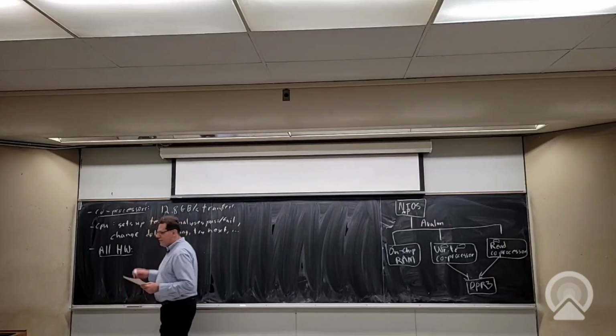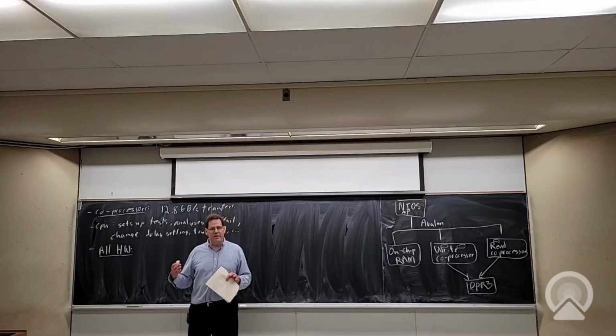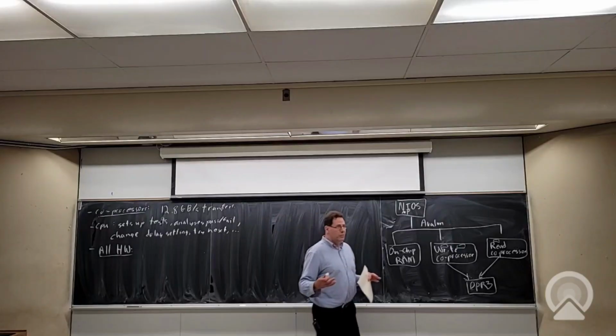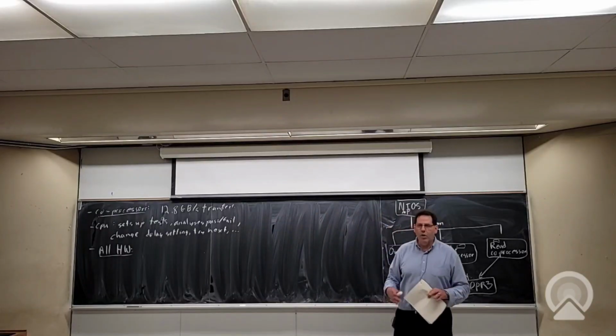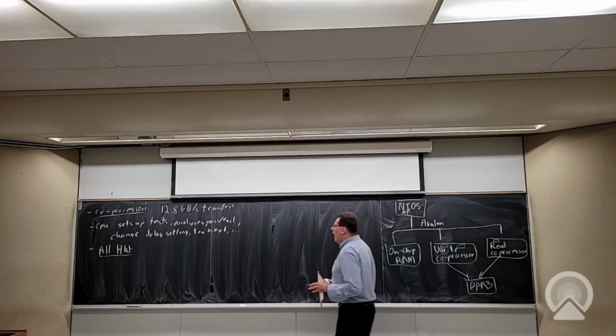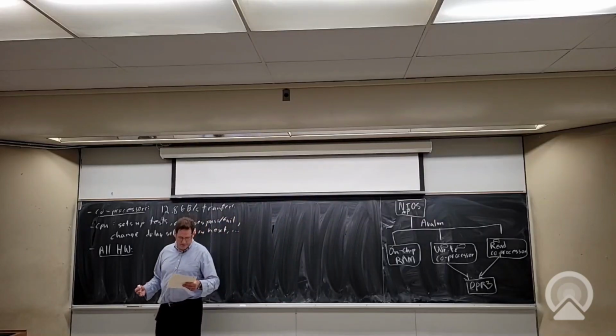And the calibration algorithm also was not fast enough. So they couldn't get to the highest speed DDR standards, and new standards kept coming out. So there was a problem with trying to keep up. It was difficult to modify an all-hardware design with a state machine controlling a data path. And the calibration algorithm still wasn't good enough. Couldn't get to the highest speeds.